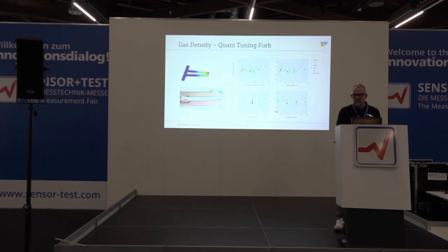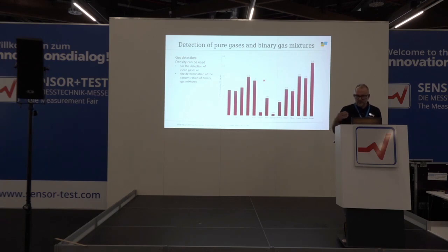Then pressures from atmospheric up to 10 bars. So that's a typical calibration procedure. So we can measure density, and these are different density or reference density at reference conditions of different gases. So you see, pure gases you can distinguish. So not every gas is easy to distinguish over density, but in most applications you are able to clearly distinguish two gases over density.